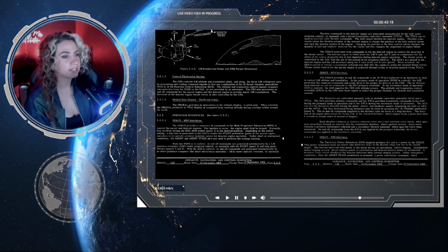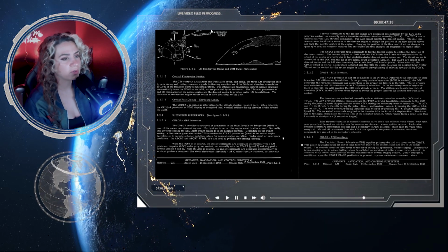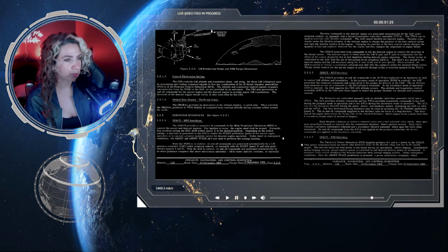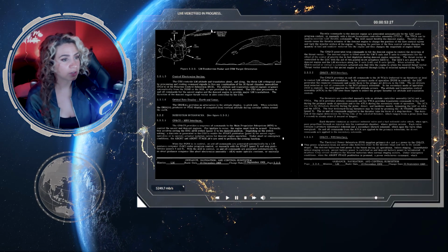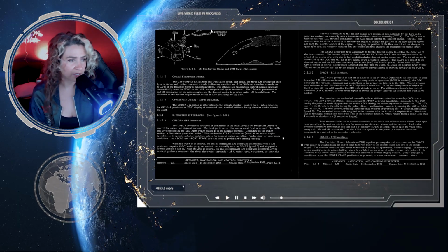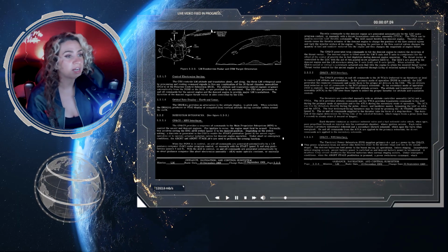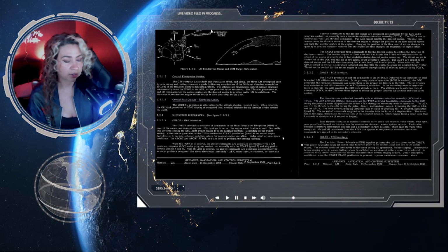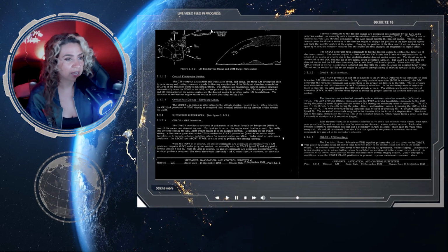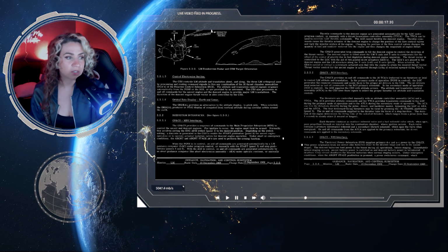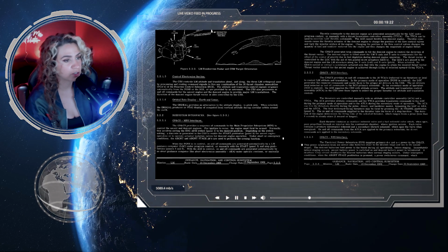Each thruster contains an oxidizer solenoid valve and a fuel solenoid valve, which, when open, pass propellant through an injector into the combustion chamber, where ignition occurs. Each valve contains a primary automatic solenoid and a secondary direct solenoid, which opens the valve when energized. On and off commands from the ATCA are applied to the primary solenoids. The direct commands are applied to the secondary solenoids.